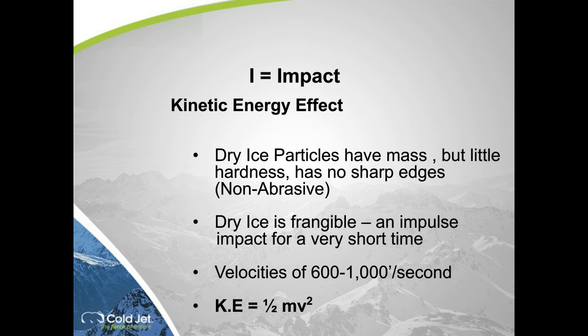When you take dry ice and apply this process to the manufacturing of medical devices, you have the ability to control the amount of kinetic energy that you bring to the process. On an ambient substrate, this is probably doing 60, maybe 65% of your cleaning. So this is where you get the biggest bang for your buck, where you make your adjustments in your velocity controls on pressure to control the kinetic energy and your particle size. Even if you choose to use 3 millimeter, you're able to knock that down with splitters, sometimes called fragmentation. You can knock down that particle size with some pins inside the nozzles that allow you to reduce the kinetic energy. That's helpful when you get on a substrate that may be gentler.